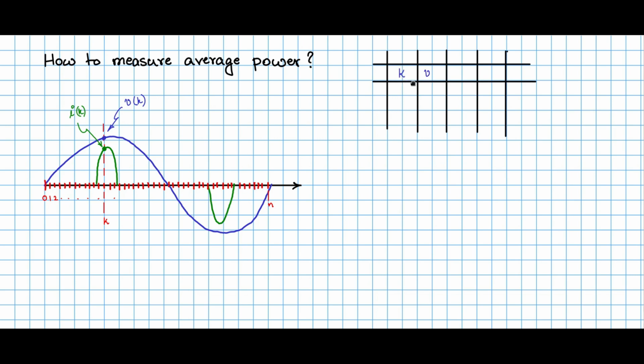Let's say you have one column for k, one column for Vk, one column for Ik, another column for Pk, where Pk is the product of these two columns, Vk into Ik. This is the instantaneous power. So for the first point, take the corresponding I and V value, V1, I1. In this case, I1 would be 0. Second value, V2, I2, and you will get P2. So on for the nth value, Vn, In and Pn, which is Vn into In.